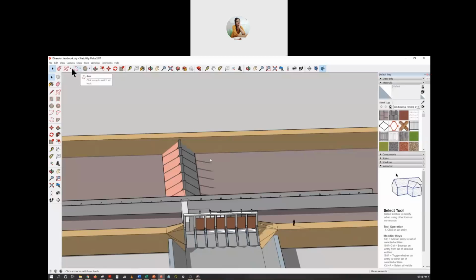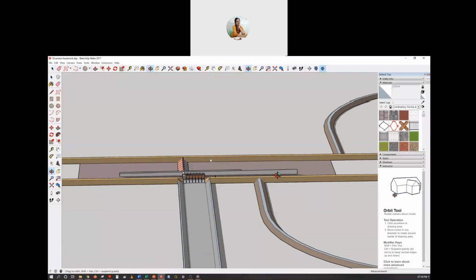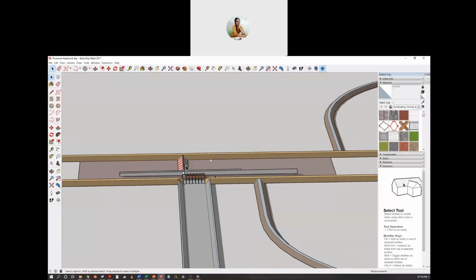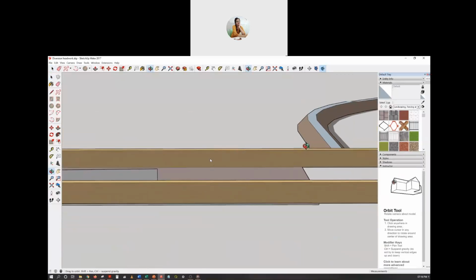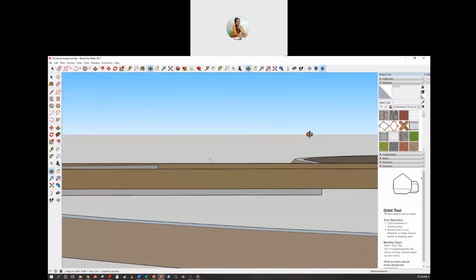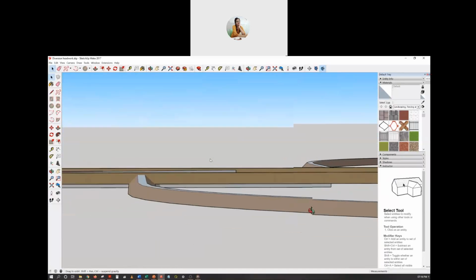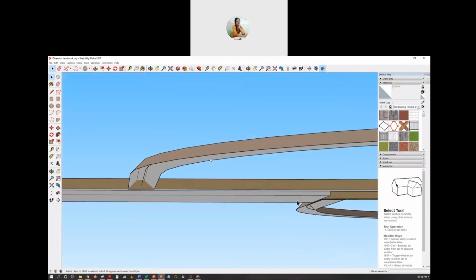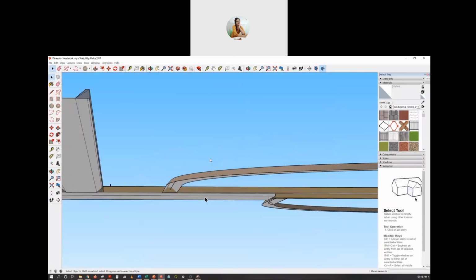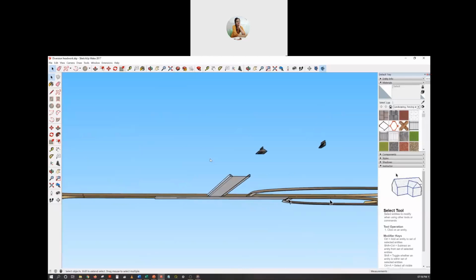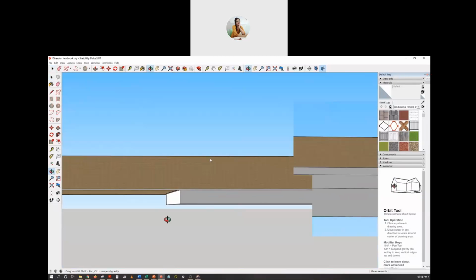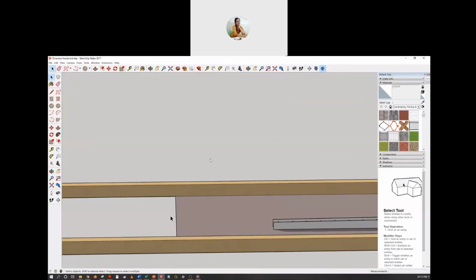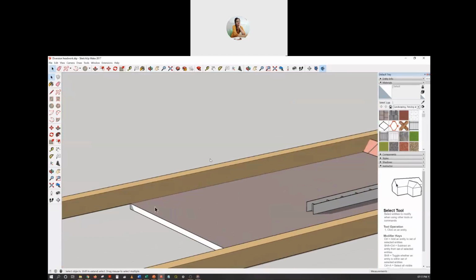So what we have done is we have provided some impervious floor so that water cannot enter in this portion, water has to enter here in this location, and it has to flow under the ground, under the floor, and through this it can release at this portion to the downstream. That means we have increased the flow path.